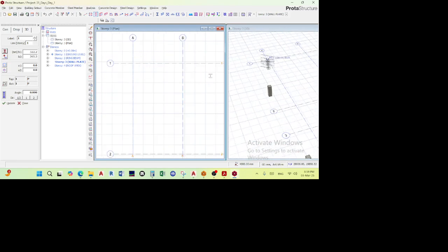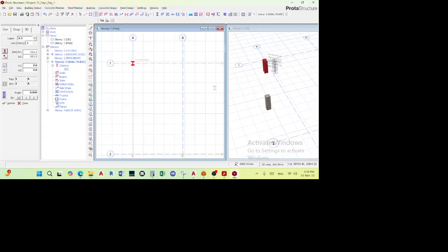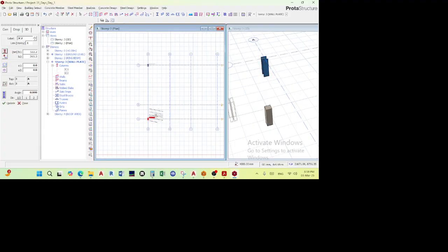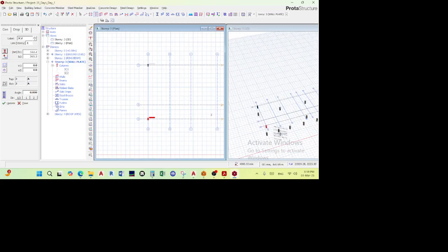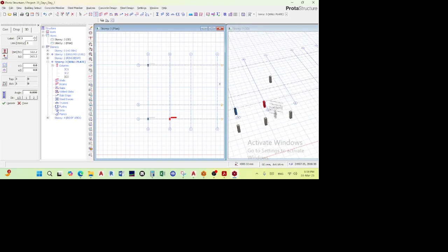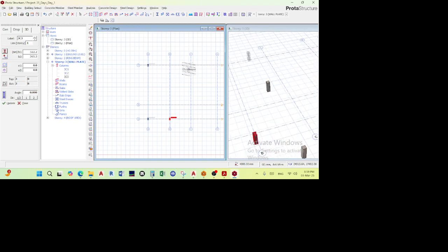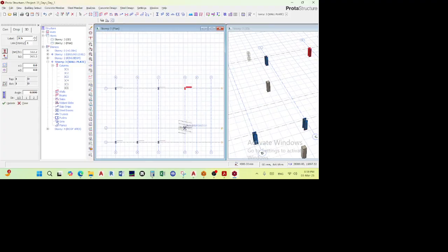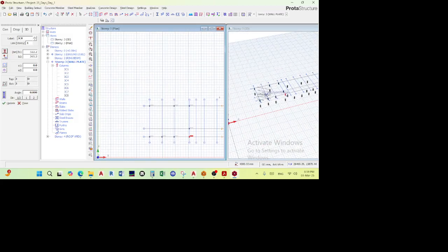You will notice that it will come from the top, even now when I try to place it, you see. Starting from where the eaves is, going down. So when I click it there, you can see in the 3D view, it's starting from the top, going down. I'll place another one here, top, going down. There it is. I'll place another one there, and then where else? Here and here. This is at C. There and there, right? Also here I know for a fact there are 3 stubs there.